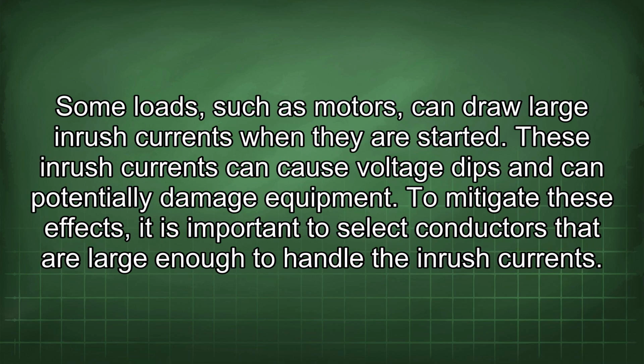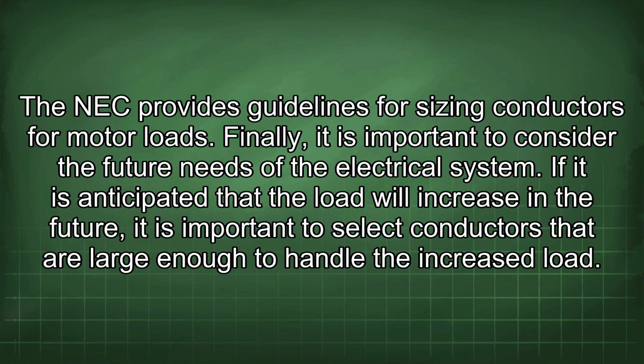Another important consideration is the type of load being served. Some loads, such as motors, can draw large inrush currents when they are started. These inrush currents can cause voltage dips and can potentially damage equipment. To mitigate these effects, it is important to select conductors that are large enough to handle the inrush currents. The NEC provides guidelines for sizing conductors for motor loads.